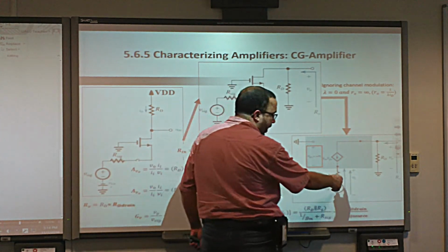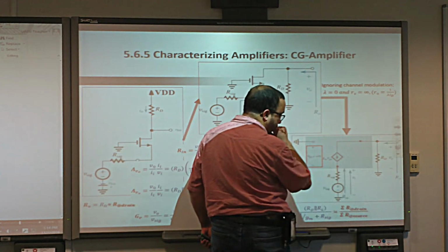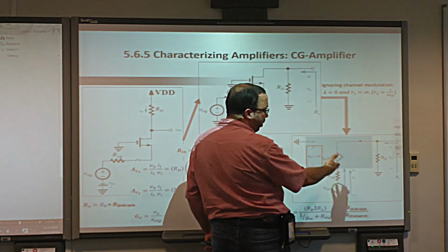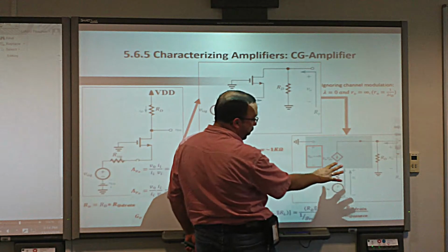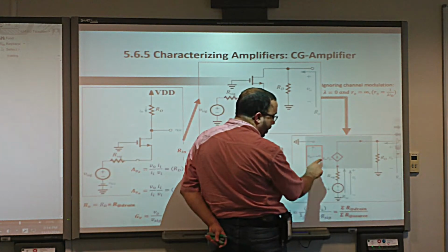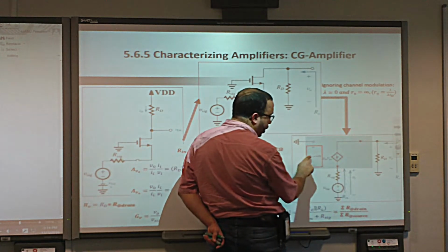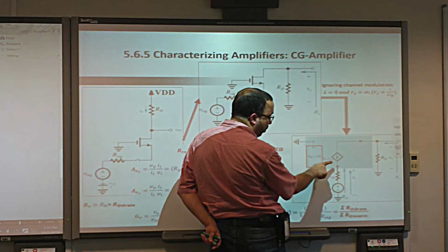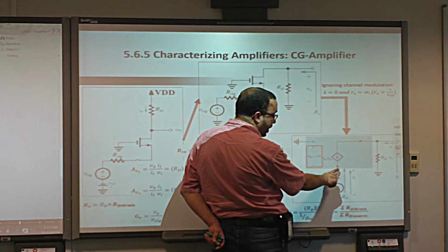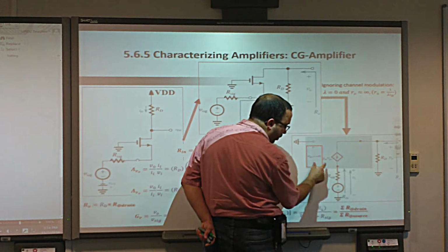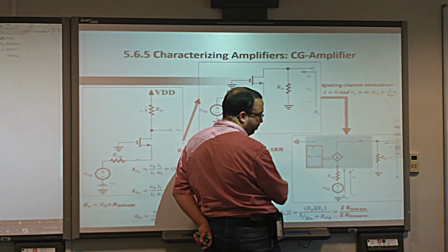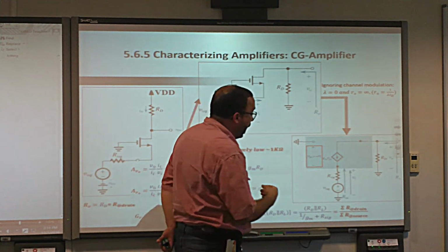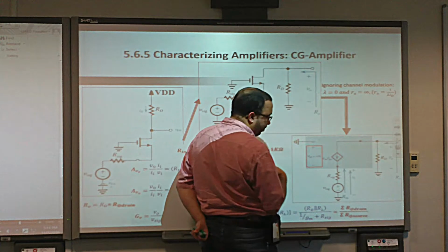So you can see here, or Ohm's law actually, if you want. First of all, before we go anywhere else, you can see that Vin here and VGS have a relation between them. VGS is 0 minus VS, and the input is actually VS minus 0. So they have a minus between them. Yes or no? This is number 1. So I know VGS is equal to minus Vin. And okay.